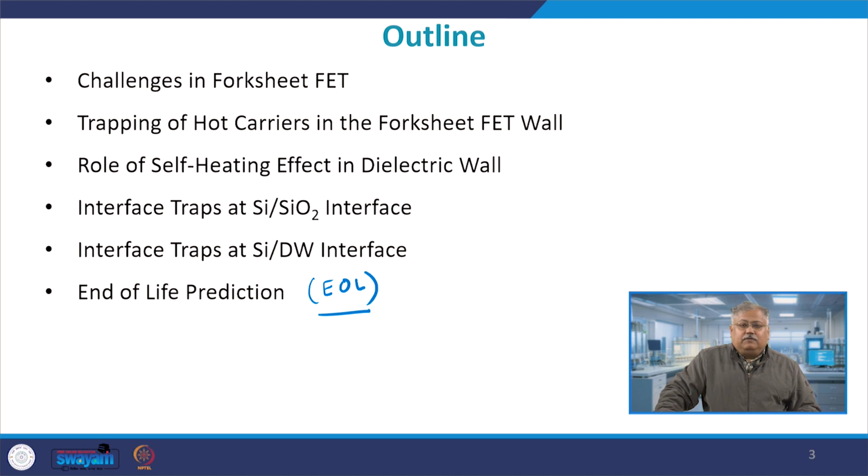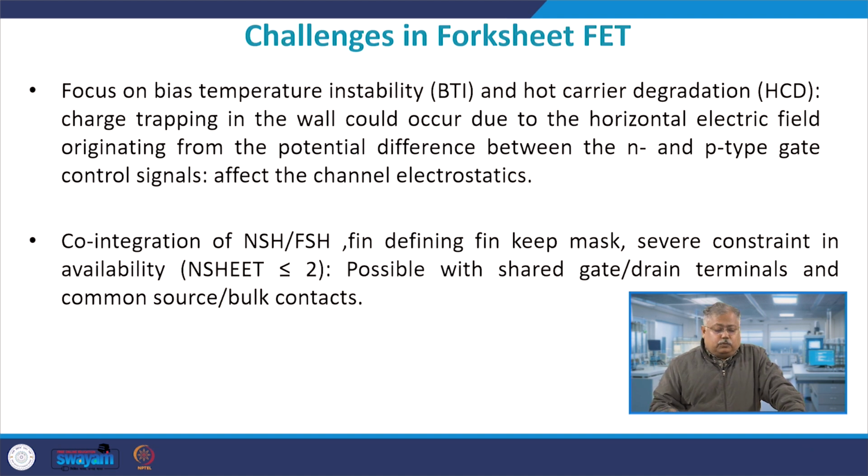And as a result, what will happen is it will dissipate energy to this wall. However, silicon dioxide being an insulator to a larger extent, it doesn't allow for the quick dissipation of heat, right? And therefore the hot carriers tend to give the energy, but the energy is not dissipated in free space. That results in what is known as a self-heating effect, and that is basically a detrimental effect which you don't want to happen, right? So what are the challenges?